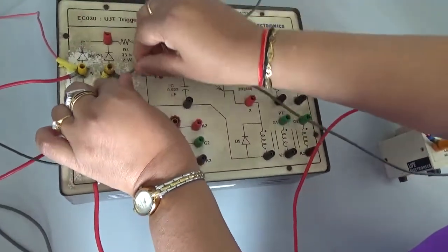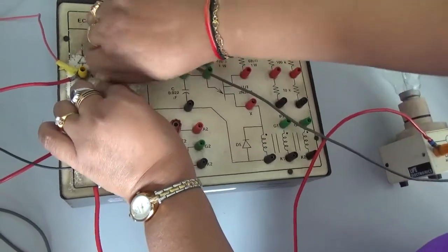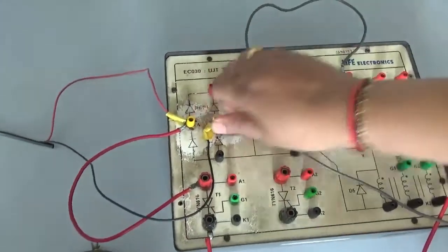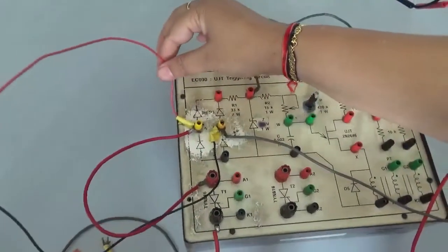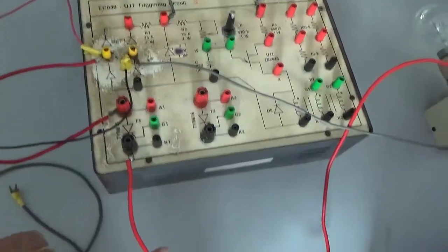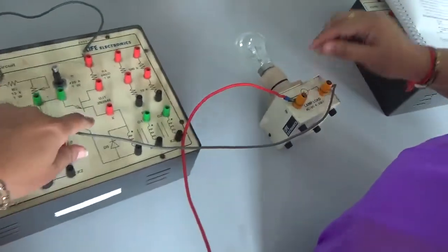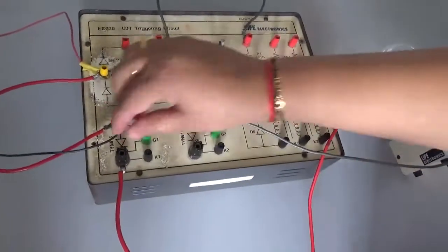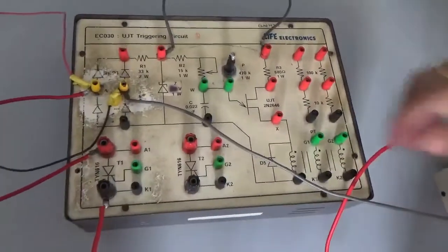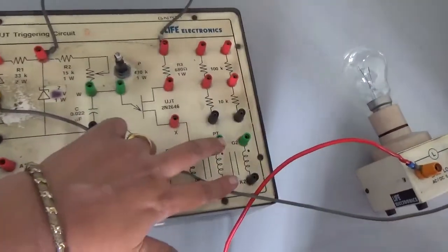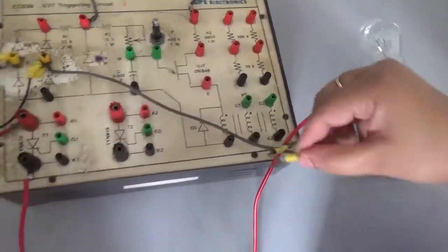Okay, this is a very simple circuit. What we have is a 230 volts supply connected across the rectifier here. From the positive of the supply, we are connecting to the anode. From the negative, it's going to the load, and from the load, it's coming back to the negative of the supply. Now we need to give the gate and cathode connections. This G1 K1 should be connected to G1 K1 of this circuit. Okay, this is very important.